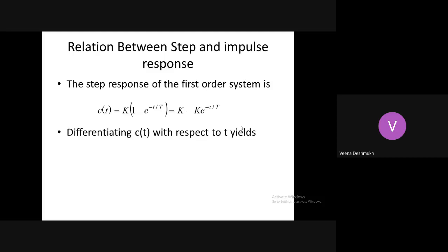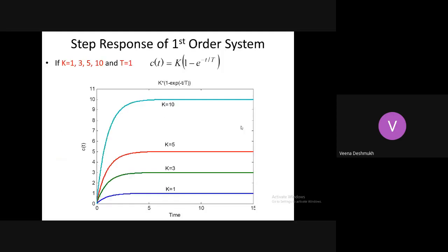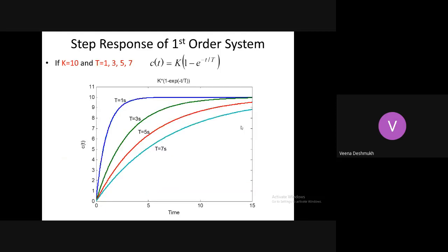The first order system, which I discussed just now, with the step input response. That is what I mentioned yesterday. For all the transient analysis, always the step input is considered as input. So with the variation in k and the time constant tau, we get these two graphs.